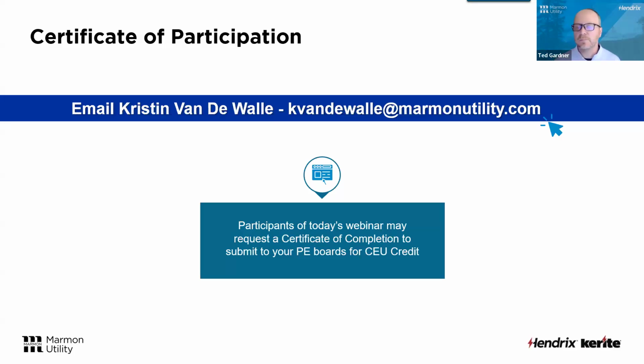Most utilities try to avoid that emergency overload, which is going to be 48 hours or less. Reliability wise and rigidity wise, it's going to be pretty comparable to HDPE. The cost is a little bit more on XLPE, but we'll let the sales and marketing folks talk about that. The big thing is that emergency overload.